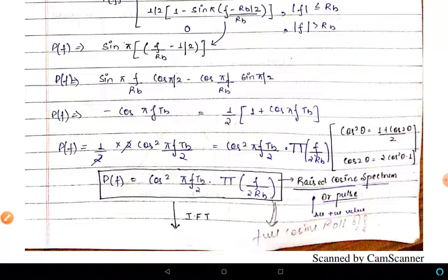So this all is a part of the Nyquist practical solution. I'll briefly recap what we have done. First, there was ISI. Why has ISI come? Because we are passing a band unlimited signal through a band limited channel. This causes the output pulse to be band limited, which causes pulse expansion. The pulse expansion is a problem because it causes interference with the succeeding pulse, and this is called ISI. What is the solution? I cannot change the channel because the channel is always band limited. So what I need to do is make my signal band limited.